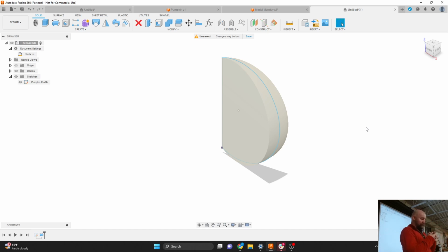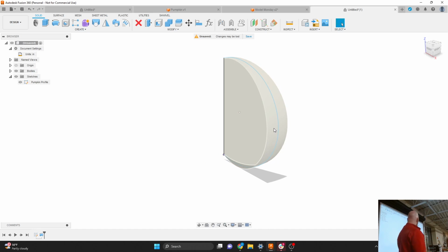All right, now let's create another sketch. So I'd like to determine the radius that is going to be how much this lobe pops out, kind of the bulbousness of the lobe. And in order to do that, I need a sketch plane that's kind of right in the middle of where this sketch is here.